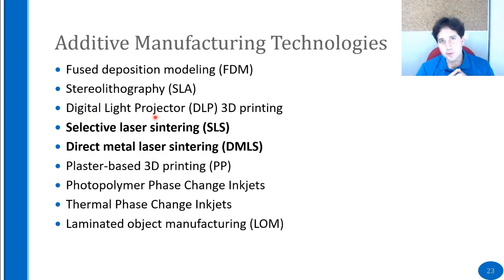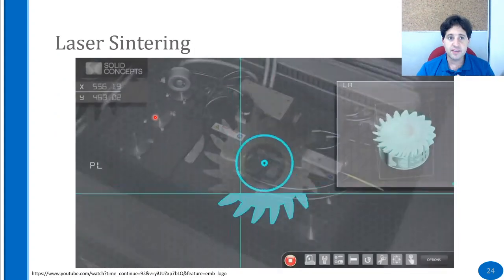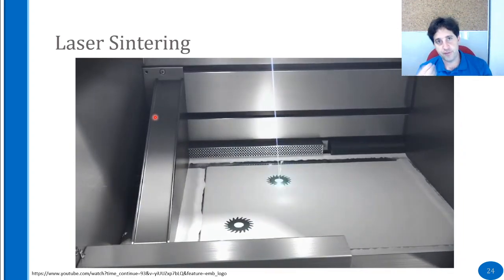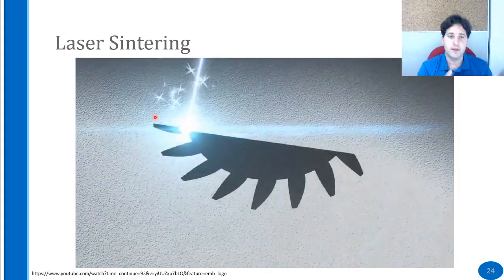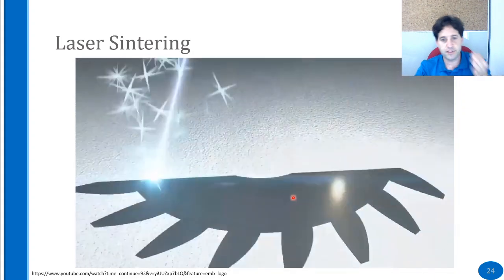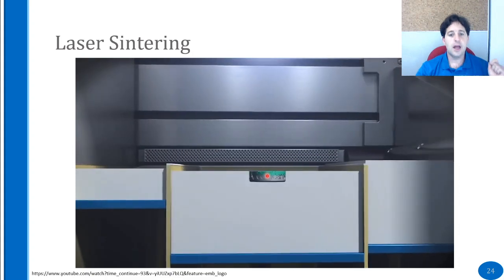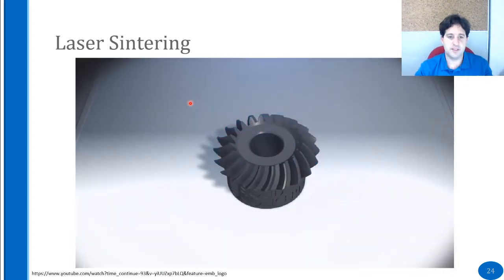The third, I think, most important technology is laser sintering, or laser melting. The idea here is that we have lasers that heat up a powder or a bath of very small particles that the laser melts into a layer of what we want. As you can see here, usually it's a few lasers combined into a single point, and this point fuses, sinters, melts, whatever verb you want, depending on the technology, and generates the layer by melting together this bath of powder.